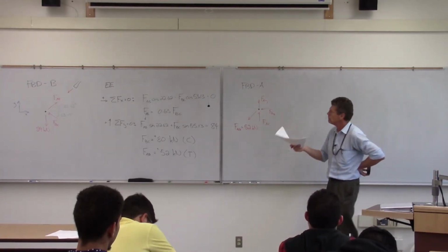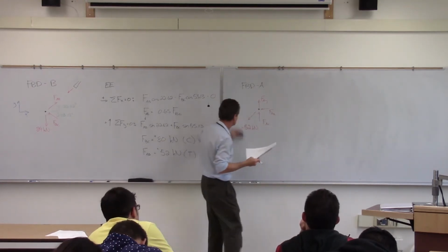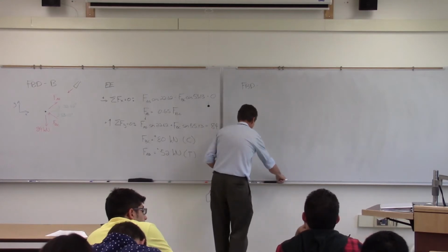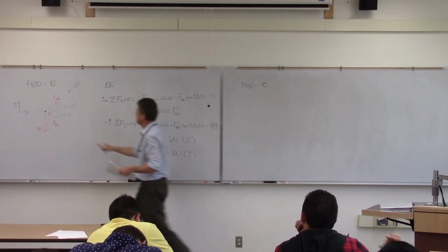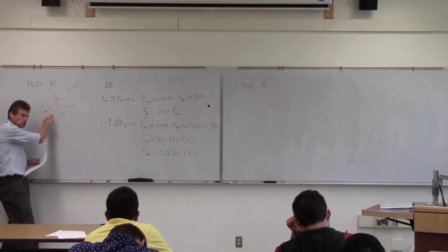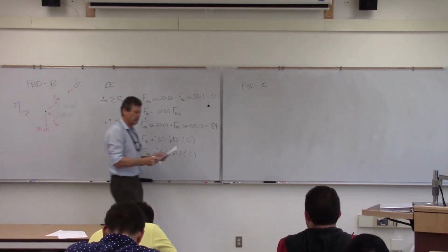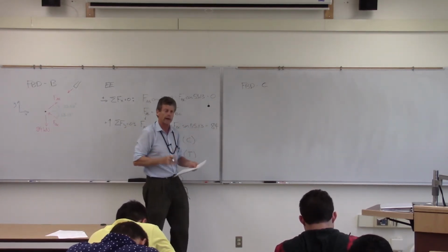But again, what we'll find is generally, everybody got this? You want to do the joints or the pins last. No, we just simply want to follow it to another joint. So we're going to follow this one. We solve for 2 forces here. I get my choice of which way I want to go. I'll go to BC. And this is something when you start solving them, you're just going to look at it and go, this is where I want to go.